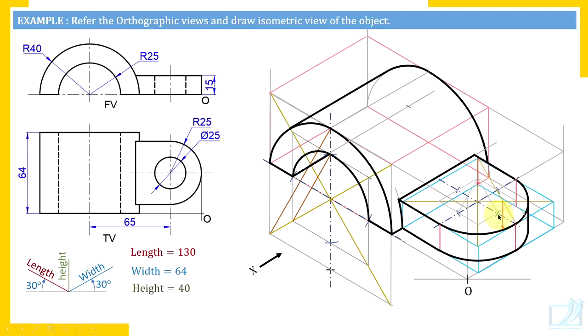So here a rhombus, 4 centers. 2 centers are the ends of the smaller diagonal and the other 2 centers. When you join one end of the shorter diagonal with the midpoint of opposite edges of the rhombus, then you create points of intersection on the longer diagonal. Those are the other 2 centers.